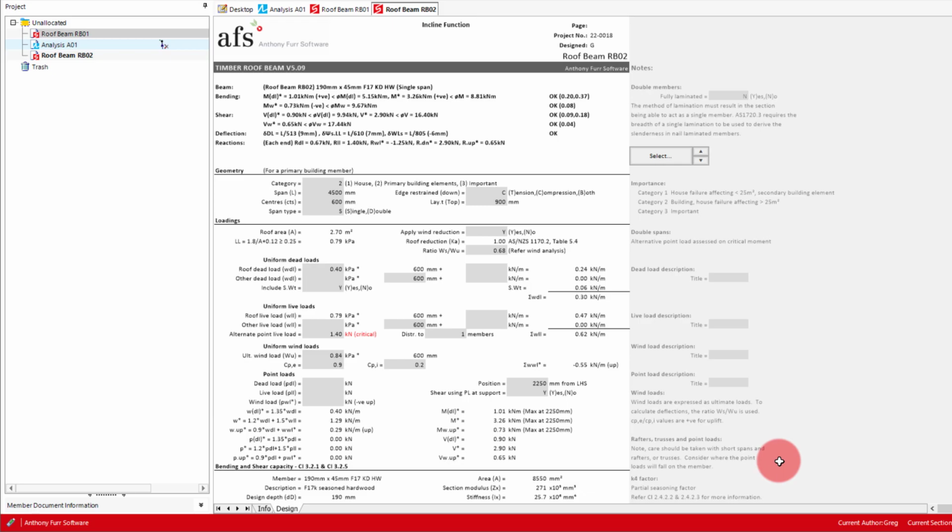Another case where you might use this is for the load width of a flat pitched roof. In our centers, we can input the incline as we demonstrated earlier. But say we also had another roof load adjacent contributing to this load width, but this additional load wasn't on an angle. What we can do is just add on at the end of the function the additional load width. And the column will also update to include this.